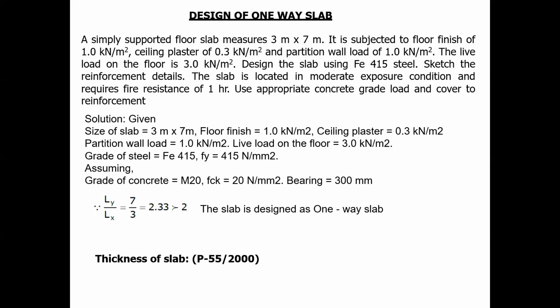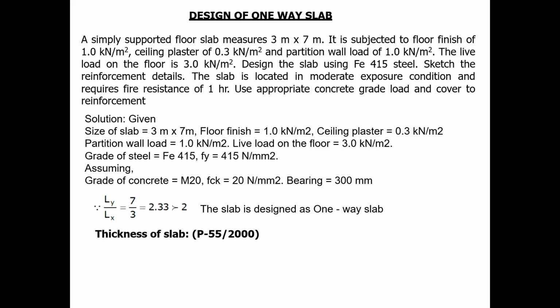Next, thickness of slab. As per IS 456-2000, page number 55, effective depth d is equal to effective span divided by 20 into MF. MF is nothing but modification factor. Okay. All of you have studied the procedure which I sent day before yesterday.